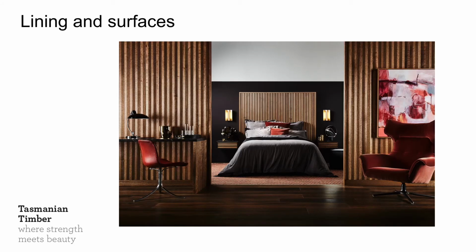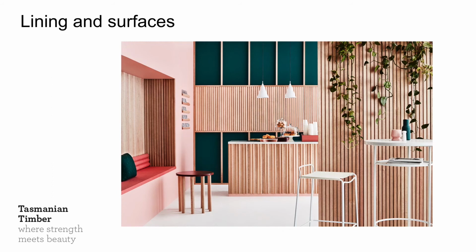Here's a slightly more considered use. This is for linings in a home. Now the detail for this is probably plywood behind with battens on the plywood to give you this indented surface. So you wouldn't necessarily use a full board behind, you'd ply it, colour it all the same, batten it off. And then you've got vertical battens applied with the trims around the door and a trim along the skirt. And the material is very open to sort of colour interpretation. So this is probably the same base material with a different profile and a different colour trim around the outside. Different lighting, of course, obviously. Photography makes a big difference.